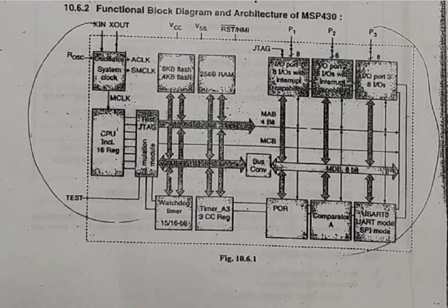The instructions of the MSP 430 are 16-bit long. Whenever we need to execute any program, there are certain things we have to keep in mind. That is, first we need to fetch the instruction, decode it, and then execute the program. First you need to write the instructions which the microcontroller needs to understand. There are 27 basic instructions of reduced instruction set computing, that is RISC format, and 24 emulated instructions of complex instruction set computing.